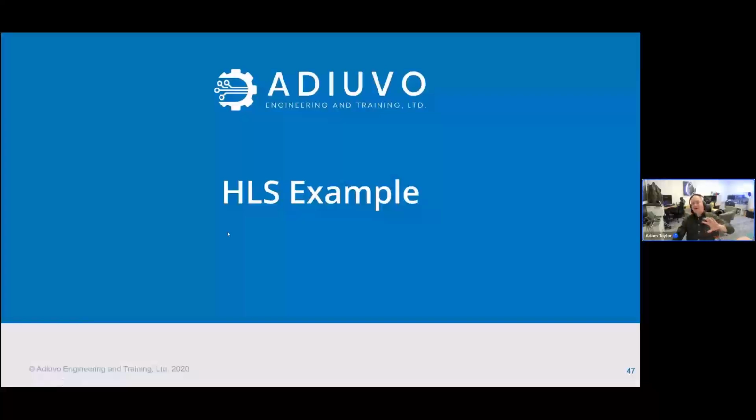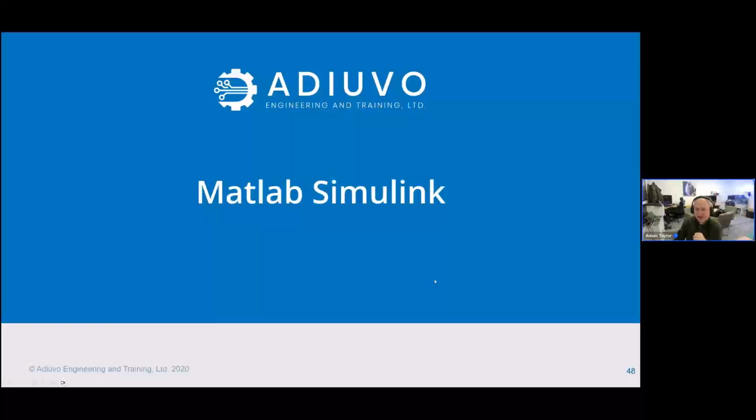So far we've looked at how we might create these things using VHDL or Verilog, the basic rules of fixed point maths, and then we've looked at how we can do more complicated functions in the FPGA. We've just touched a little bit on HLS and how we could use HLS to help us. The final thing I want to wrap up on this is we do a lot of model-based design, so we use a lot of MATLAB and Simulink, and of course this is available using the Vitis Model Composer as well. There are elements that you can do that if you want to.